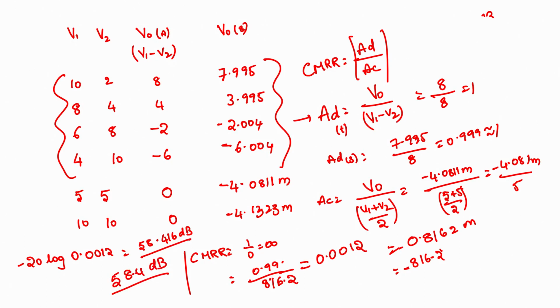Suppose we are taking a different op amp, I do not know what op amp or make we have considered in the simulation. We have simply used the op amp that is available there, right. So, this is how we generally calculate the dB of our differential amplifier. Moreover, since we are not going to apply almost a common mode signal, and even if we apply we get somewhere in the milli range, it is negligible. So, we can simply go with a difference amplifier itself.